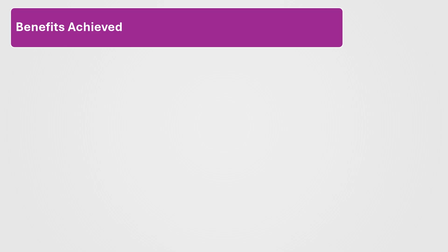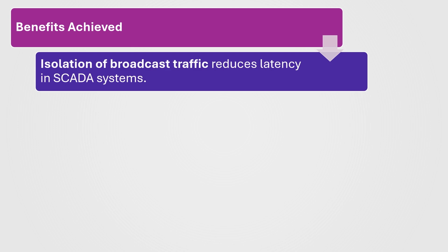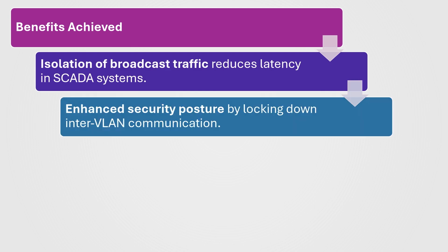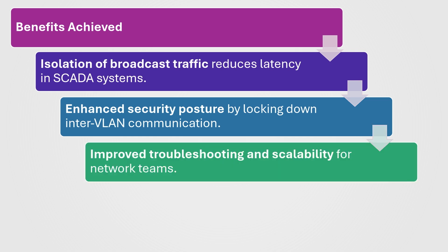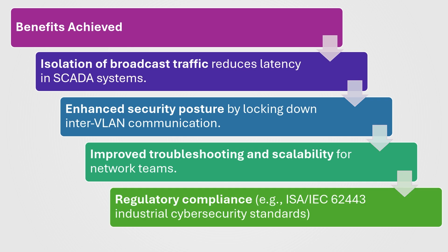So the benefits that you achieve in this scenario: you have isolation of broadcast traffic, which reduces latency in SCADA systems. You have enhanced security posture by locking down inter-VLAN communication, improved troubleshooting and scalability for network teams, and regulatory compliance, which is the industrial cybersecurity standard.